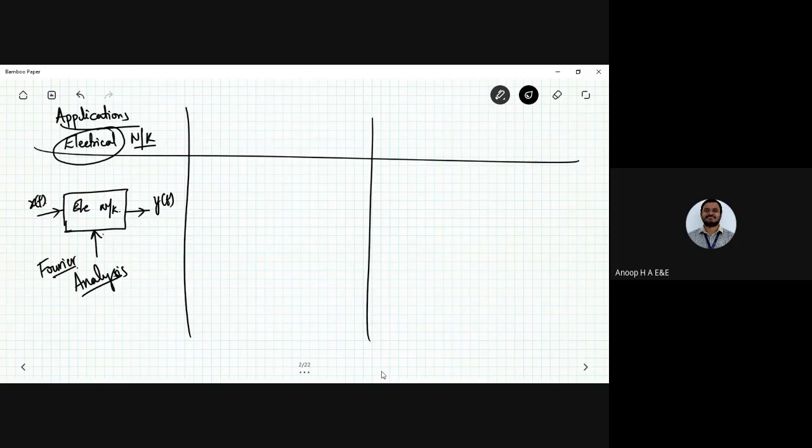So depending on the spectrum that you are going to get after giving the pulses to the given switches, in order to analyze that spectra, okay, spectra is nothing but a wide range of harmonics that are present there. Either it might be a magnitude or amplitude spectra, or you can call it the angle one. Okay, so you have a complex quantity which can be analyzed by both the magnitude and the angle there. So in certain ways you are going to analyze using Fourier analysis, which becomes a mathematical tool for analyzing a given system there.